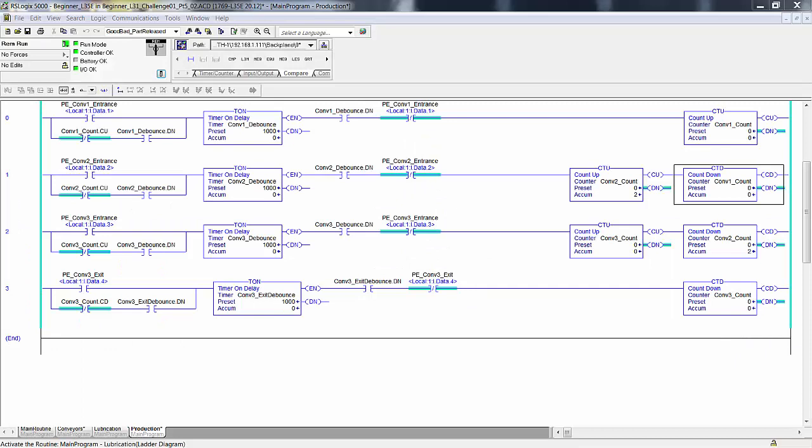Looking at our examples on pages 244, 245, easily recognized, most of the page is covered with the individual steps of cartons as they move onto the two conveyors. So in the very first illustration, that's what you should be looking at right now. Carton or the object arrives at the entrance to conveyor 1. You have a photo eye, 1 PE, blocked. So logically, the decision is to run the conveyor or wait for logical conditions.